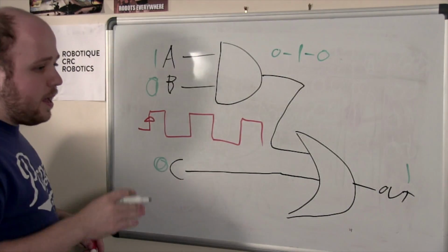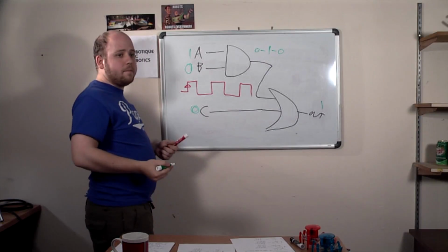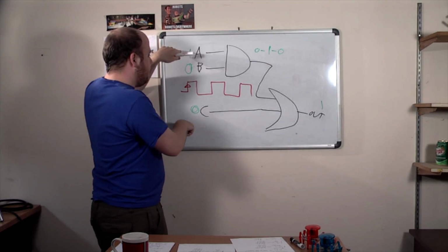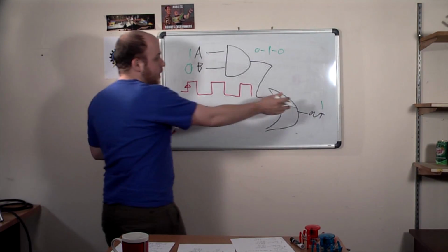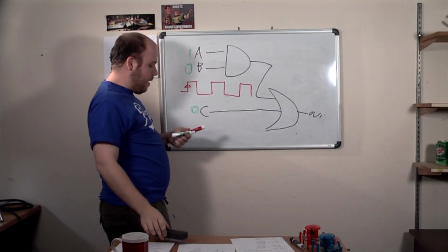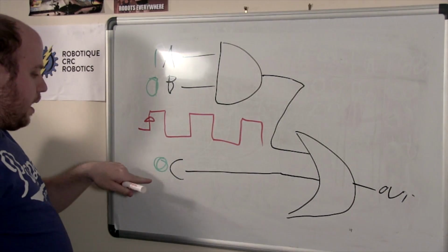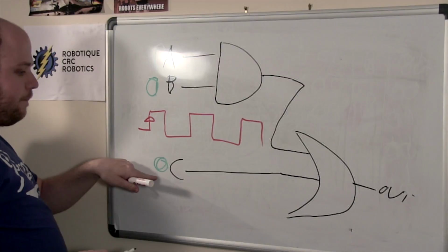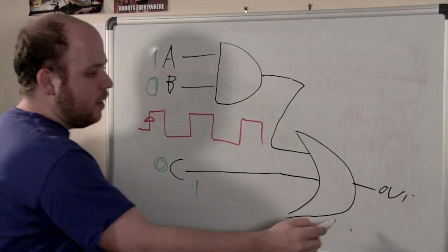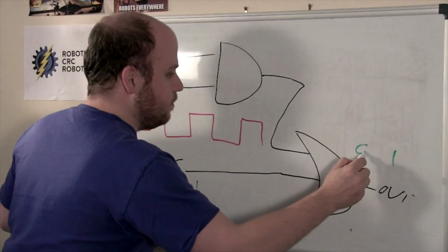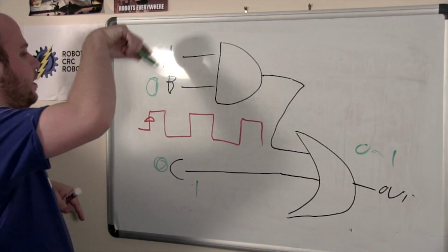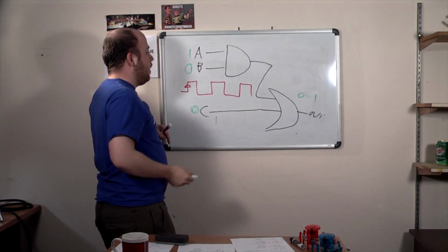The problem here is that when you're using clocked systems, sometimes the propagation will not go right. For example, if I'm switching both bits at the same time, let's take a look at the output. At C, I'm switching from 0 to 1, okay? At the first time it will immediately go from the 0 initial state. At the next clock, it will go to 1, regardless of what's going on over there.